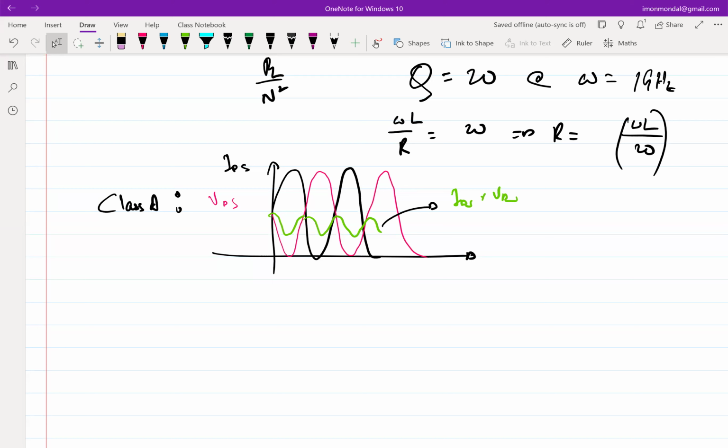When the voltage across the load increases, that is fine. All the current is going into the load. Most of the current is not going into the MOSFET. But when the current in the load is decreasing, that current is going into the MOSFET, and that is contributing to a lot of power loss. What if I find a way of nullifying that part? I'll keep the good part, that is the current going into the load. That cycle I should keep. The other half cycle, in which the current is being diverted to the MOSFET, I'll not keep.